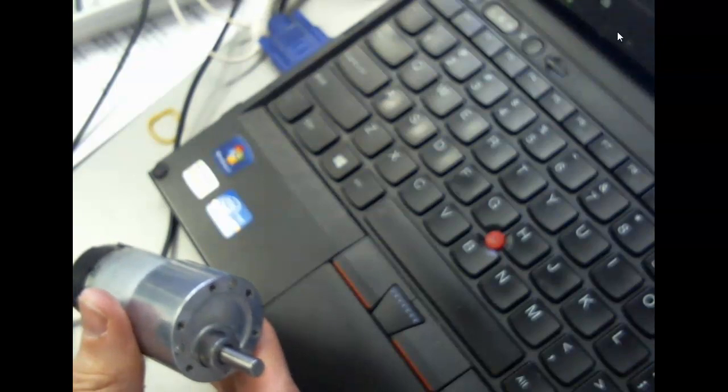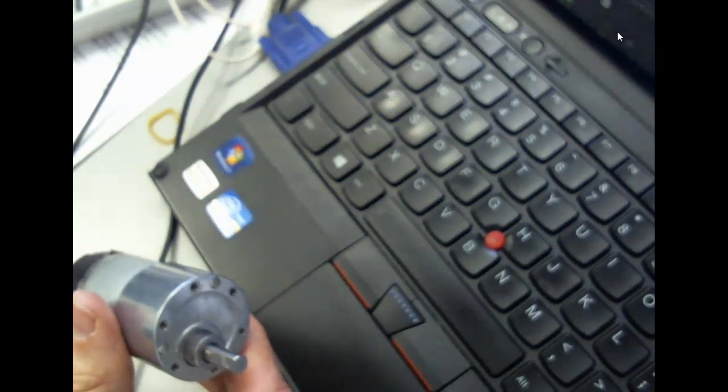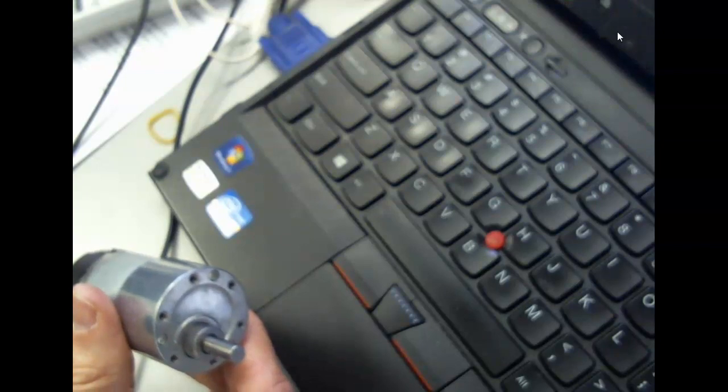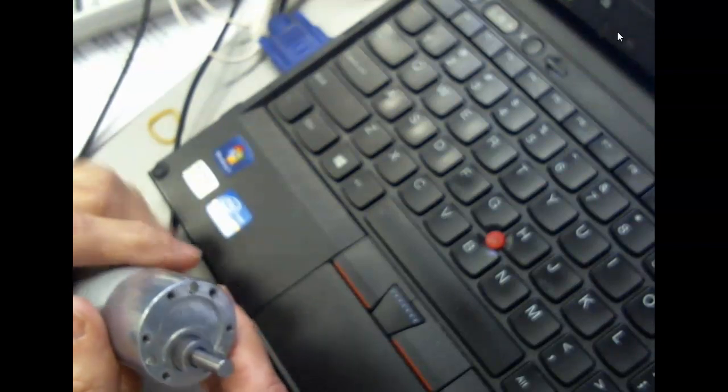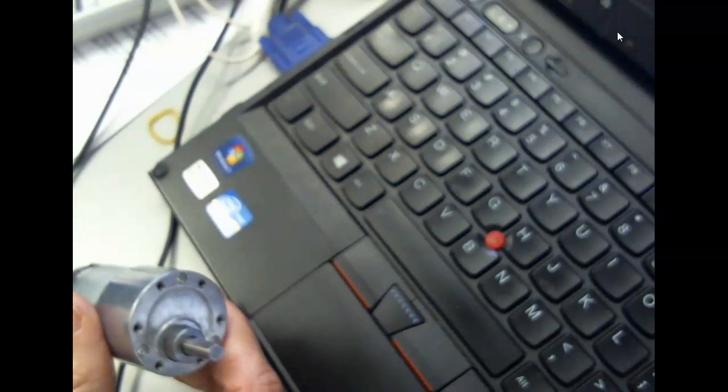So what can I get off this thing? I could get position. If I counted, I could get position. Since it's a quadrature encoder, I could also get direction, and I can also calculate speed. So this is the advantage of these quadrature encoders. With incremental encoders, we can get counts and speed. With quadrature encoders, we can get counts, direction and speed, right? So I've got one sensor that gives me multiple things.